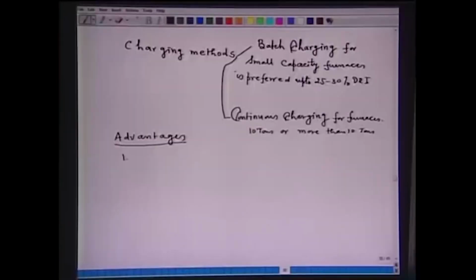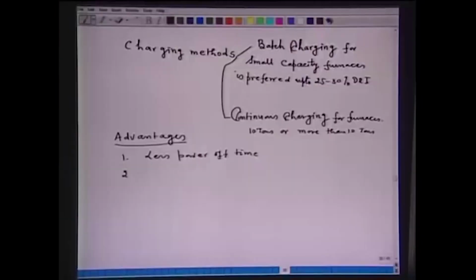The first advantage is less power off time, because now you do not need to switch off the power while charging as in case of batch charging. Second, heat losses resulting from delays are eliminated.